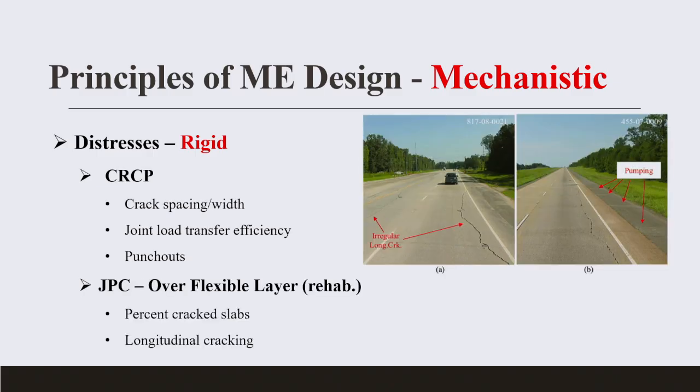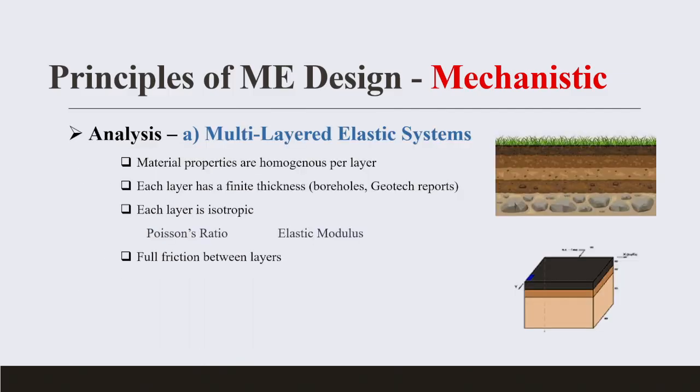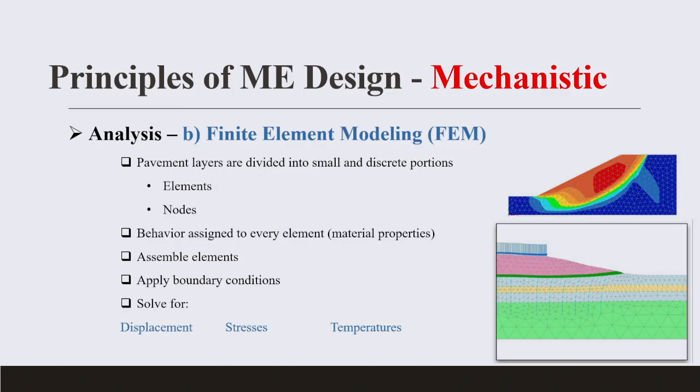So with that, I've tried my best to introduce the analysis, the multi-layer system. I talked about the mechanistic, how the analysis is done. And now there are advanced analyses that you can use, and they're actually implemented in the system. So FEM is implemented in the system and is able to give you your stresses, your strain, and deflection at different temperatures. Those of you working on this, you can look at a simple software like Plaxis,